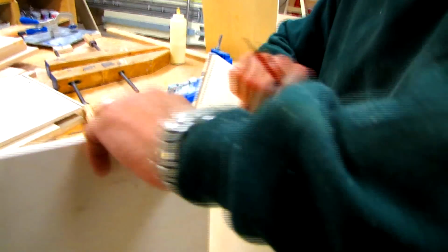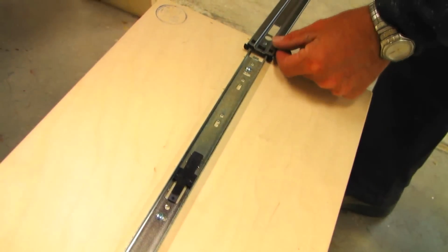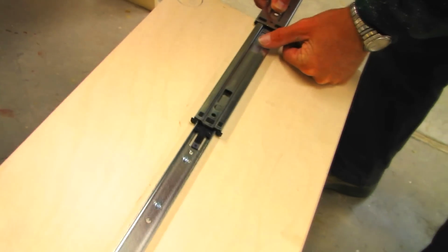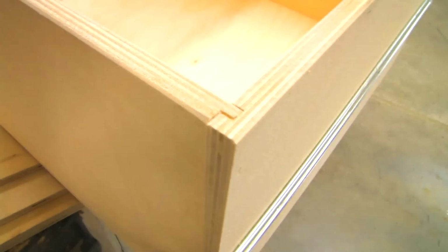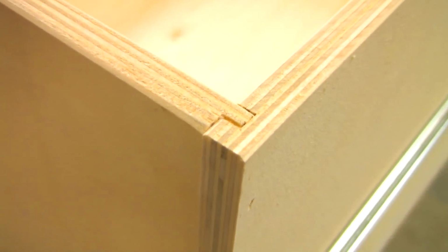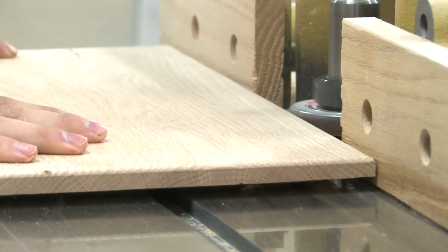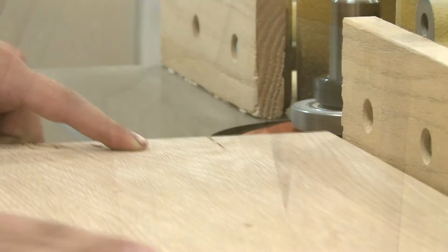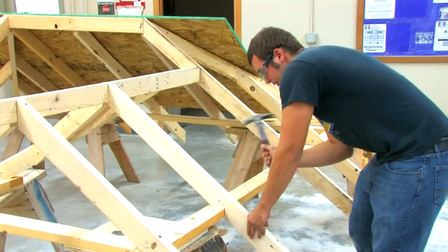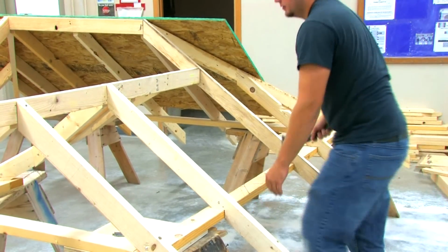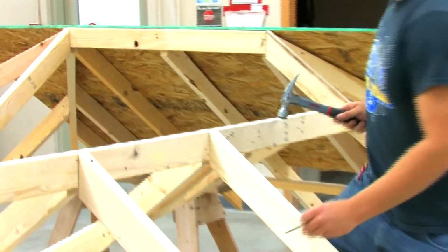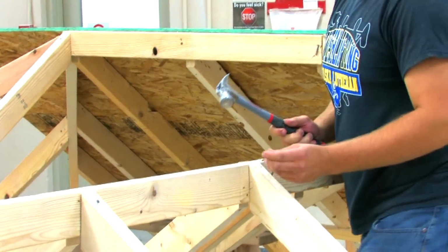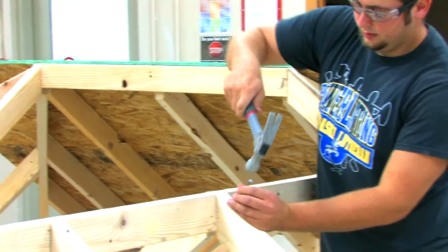Drawer sizing is the next step, being custom made to fit the drawer glide chosen. Use of the dado, plow, and rabbet joints help to adequately assemble the drawer. Before any of the cabinet doors are constructed, a graded door exercise made of pine having a cathedral arch must be completed. During the fourth quarter, students will work with a roof mock-up built in the lab. This exposes the students to some of the theory about roof framing and their complexity to build.